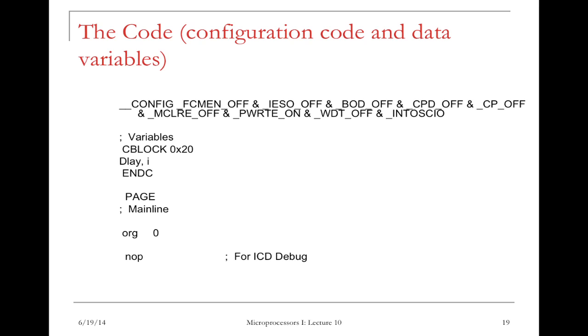To give you an example, for driving the chip, many PIC microcontrollers can use an internal oscillator or an external oscillator. Even for the internal oscillator case, you may choose to run the processor at different frequencies, 16 megahertz or 64 megahertz or 8 megahertz. Those features are controlled by specific control bits. Inside the PIC microcontroller, there's a small amount of memory called the configuration memory. With lines like this, you will set bits in that memory so that the PIC microcontroller will know, okay, I'm going to use my internal oscillator running at 4 megahertz.